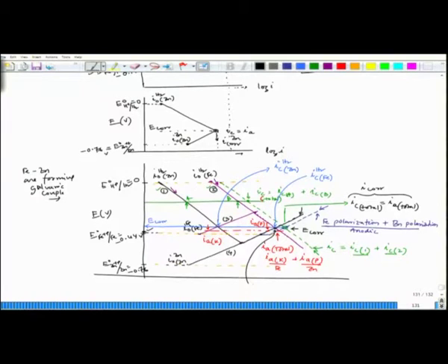this point is cutting on the zinc anodic polarization line. So, this is IA zinc, and here also it is cutting the iron polarization line. So, this becomes IA of iron. So, now if we combine them, this combination of this and combination of this, that would lead to the condition which is IC total equal to IA total.